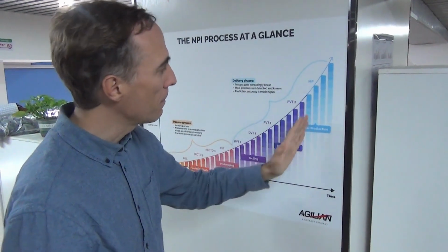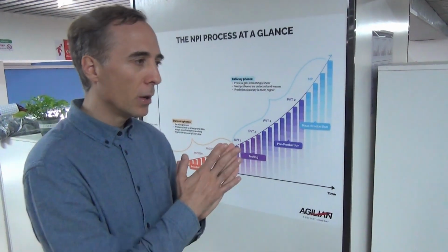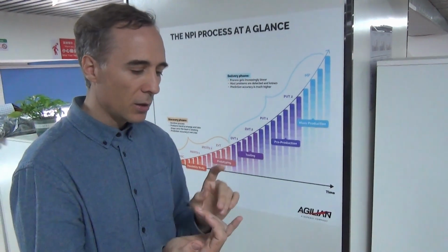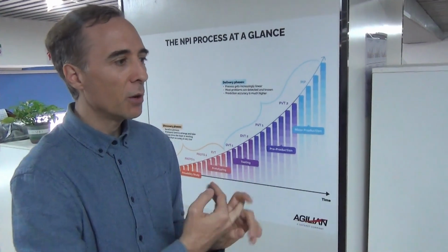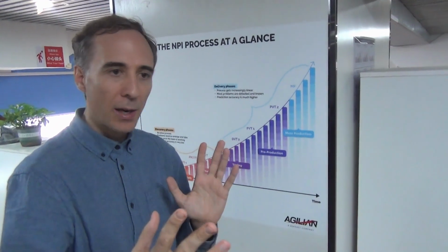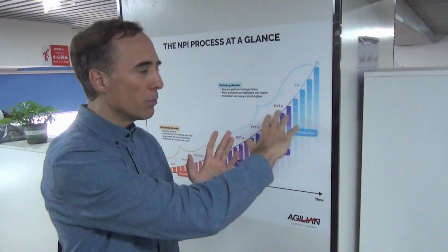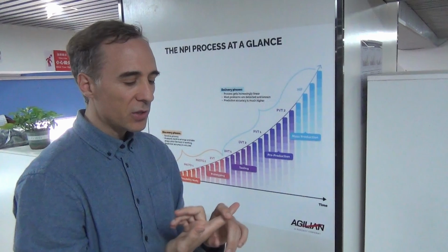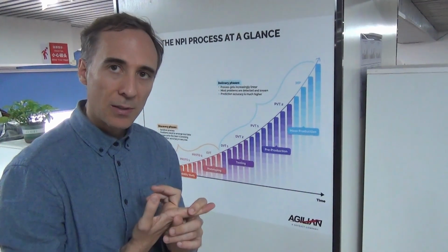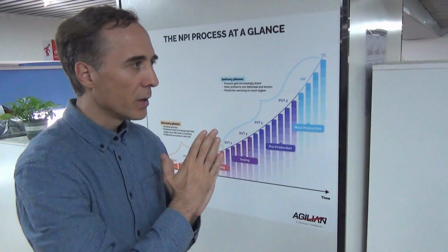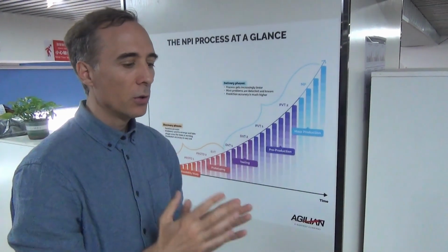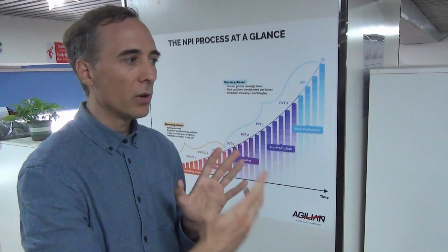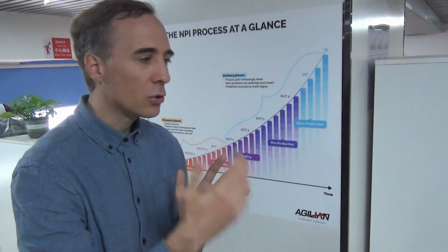Ramping up means you have indicators like scrap rate and yield, meaning how many products are good the first time, and you want to improve on them over time. You also need to improve the pace, to be able to make more and more product. So the existing lines need more semi-automation, better fixtures, better jigs.